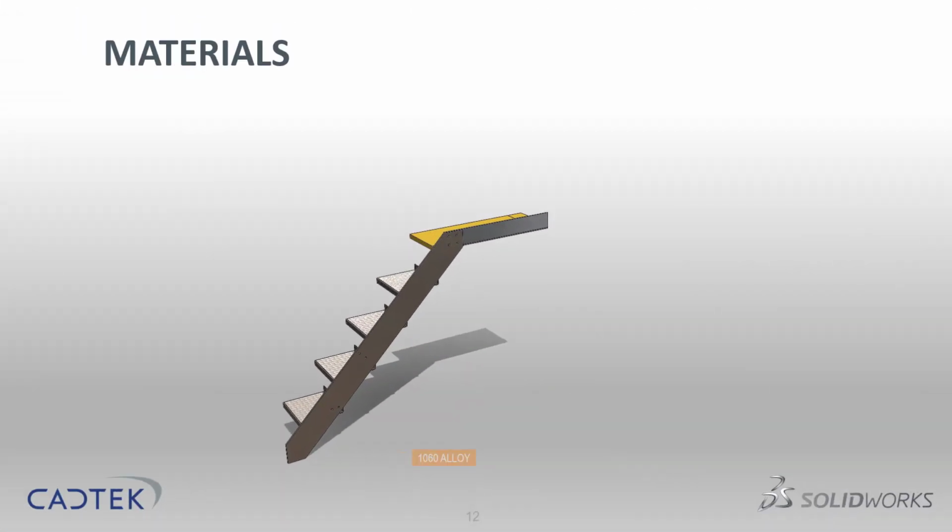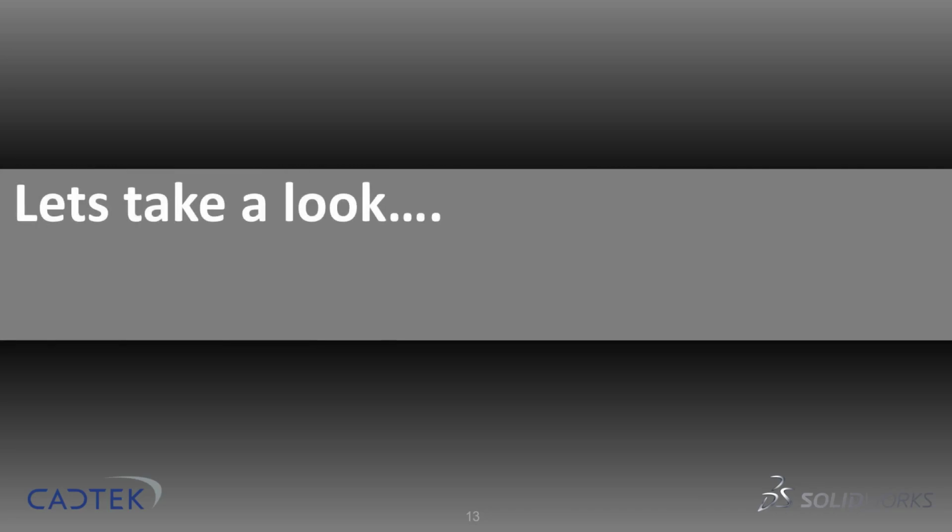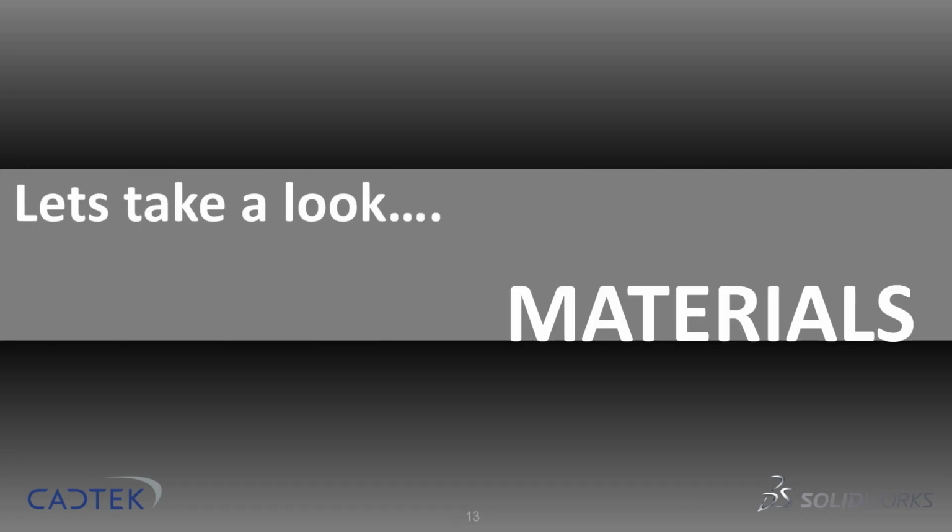The majority of the materials for this design is 1060 alloy. That includes the stringers and the top gantry pole. The treads are using 1060 alloy tread plate, but the tread plate does not affect the strength, so we can just assume it's 1060 alloy. The Eurograte, we had to create a bespoke material. That was taking the material properties that was available from their website. Okay, let's go into SolidWorks again and just make sure it's transferred those materials across.